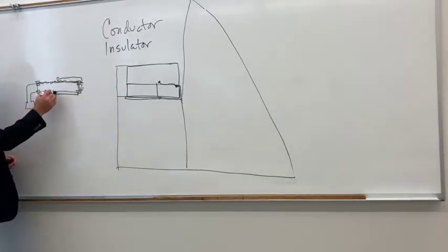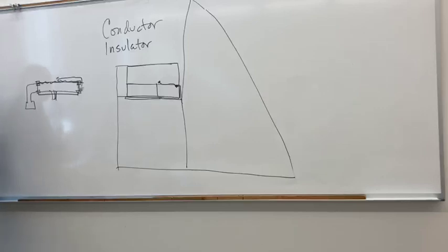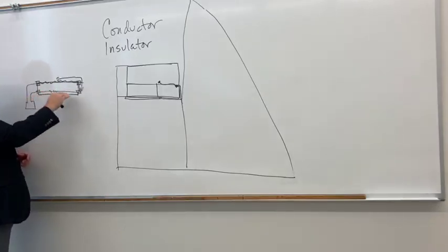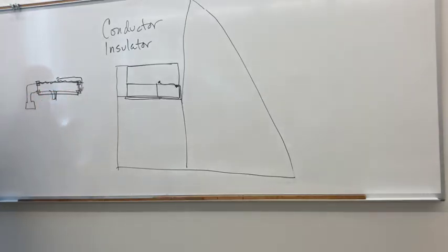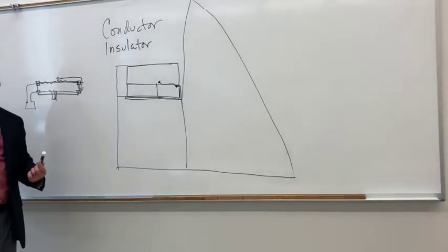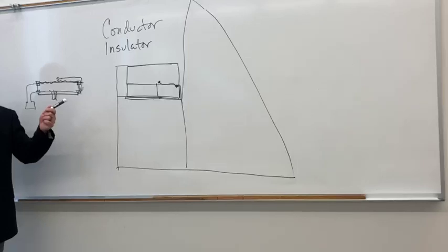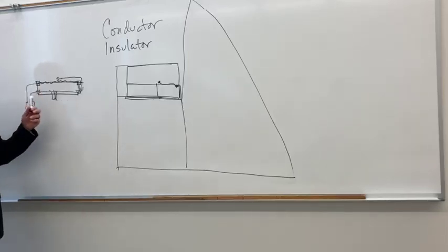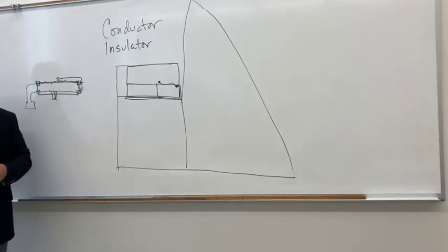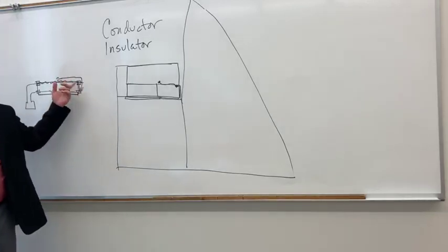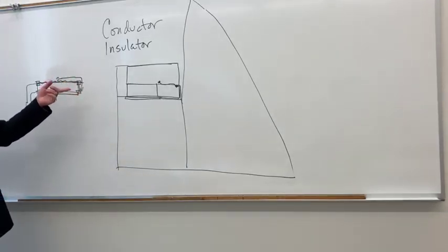So now the grass grows up and it hits right there, and what you've got is a short circuit. So periodically, you gotta walk along, and you gotta pull up the grass or cut the grass and make sure it's not touching the wires. I'm a cheapskate, I really am. You can buy these things that test electric fence generators and whether or not you've got good conductivity, and they're like $7 at Lowe's. I ain't buying that, because I can touch that and tell you whether or not it's working, right?